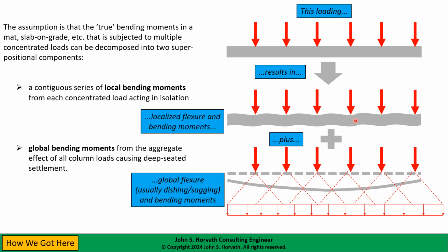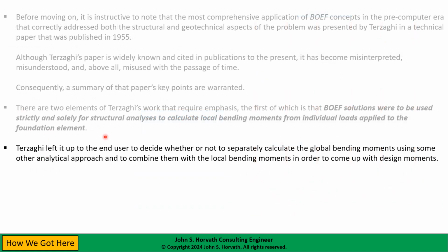So strictly speaking, the bending moments from these two components should be added together. Now, Terzaghi left it up to the end user to decide whether or not to separately calculate the global bending moments using some other analytical approach that he did not get into, and to combine them with the local bending moments in order to come up with a design moment diagram.